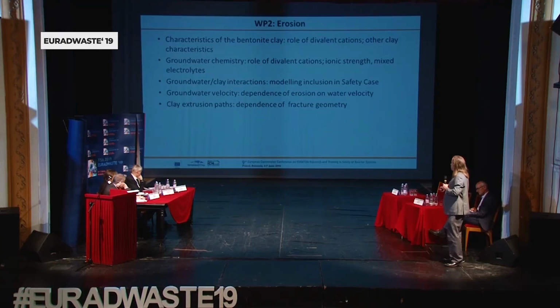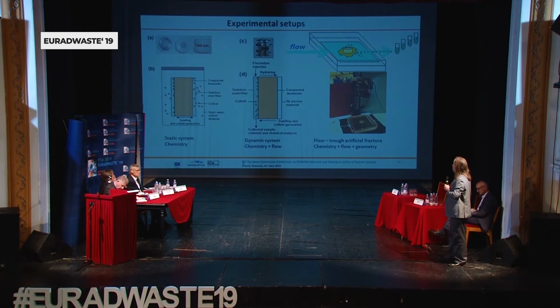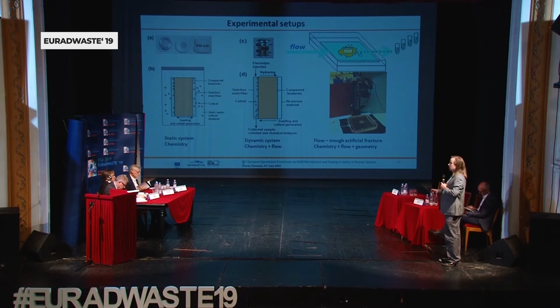Work package 2, erosion. That's dependent on the bentonite clay, the groundwater chemistry, the groundwater clay interaction, and that is how you model it in the safety case, the groundwater velocity, the clay extrusion path, and the fracture geometries. What do the fractures actually look like? Different types of experiments were employed, like static experiments where colloids are formed in a filter. You can do the same thing, but with a dynamic system where you pump.